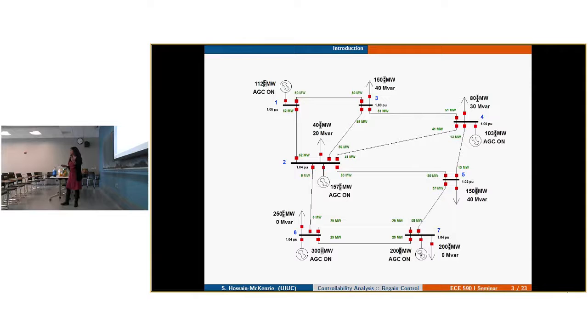Just to illustrate what I just said, say we have the 7-bus system, and we assume there is a controller on every line. When certain controllers become compromised, as shown in gray, this research is trying to figure out what the role of these distributed controllers is. Are they critical or redundant to the system control? Or which controllers help each other most so we can mitigate the effects of these compromised controls and also try to regain system controllability?